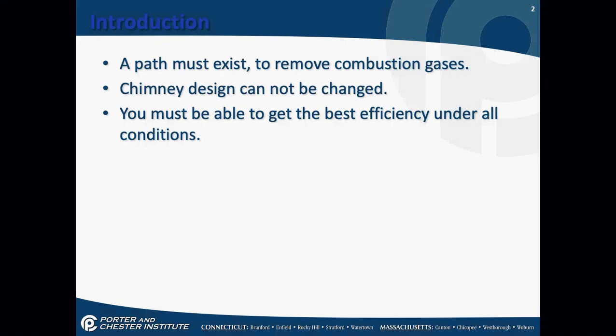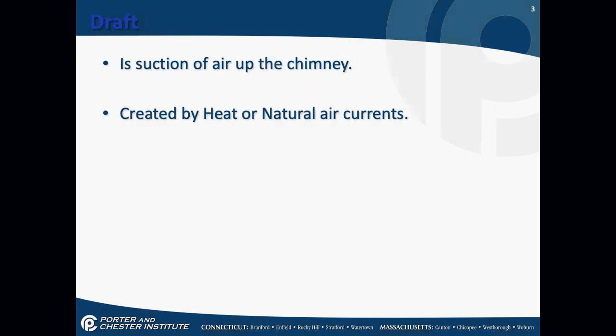If you're on a hot summer day and your boiler or hot water heater is running to provide hot water for the house, we still have to have the chimney venting properly even though it's a hot day and there isn't as much of a draft. So the chimney has to work in all conditions without changing out chimneys. You can't change a chimney.